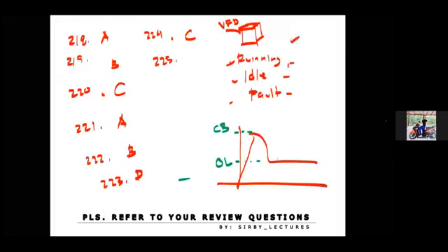Also for letter B, install a gear motor. Actually, the reduction for a gear motor is quite high as compared to the belt drives. Because in the gear motor you can have something like 1:10 or probably 1:15. So letter B depends upon the gear reduction. And for letter C, install a belt drive, then actually you can do this. Okay, so I guess the answer here is letter D.